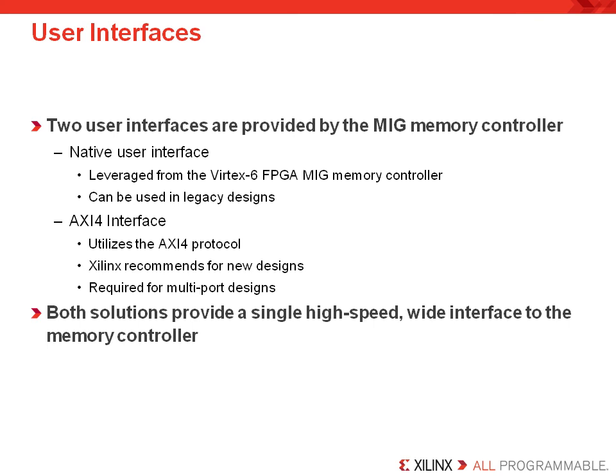Now both solutions provide a high single speed and a wide interface to the memory controller. But note now, the AXI is not a PLB bus. It's not tri-stated, it's not multi-drive, and it's not a master-slave. It is designed as a one-master, one-slave protocol. So if you want to learn more about this, for more information, you can check out the AXI interface from the support.xilinx.com website.